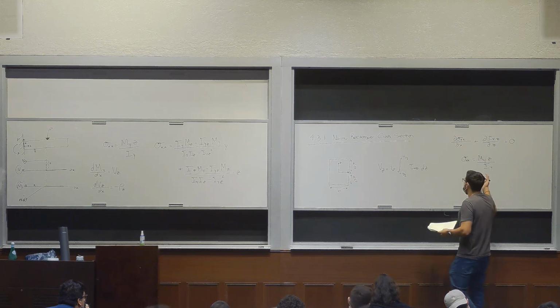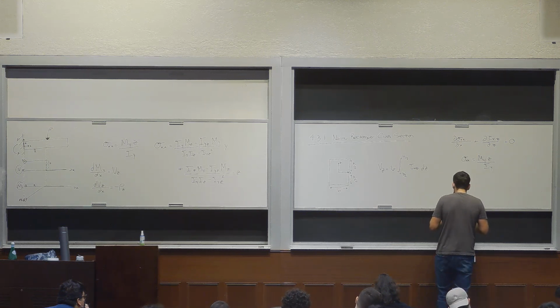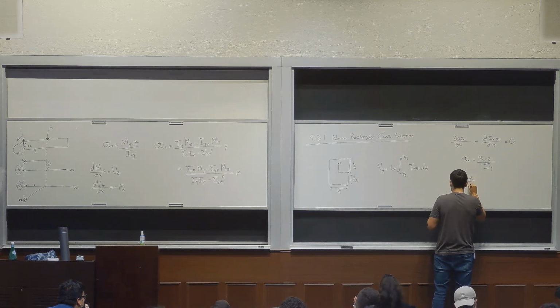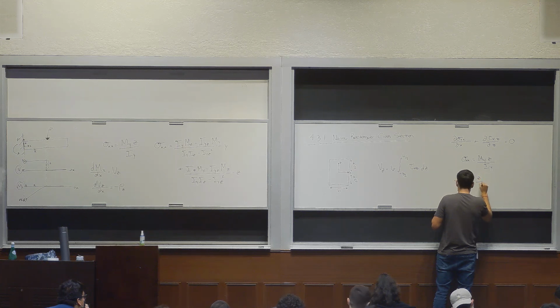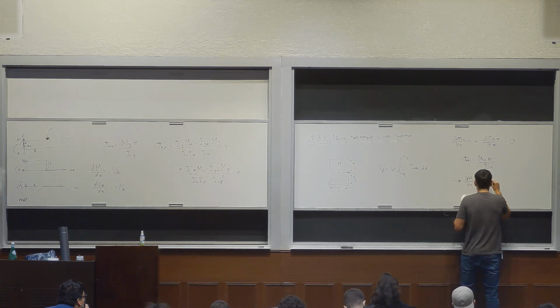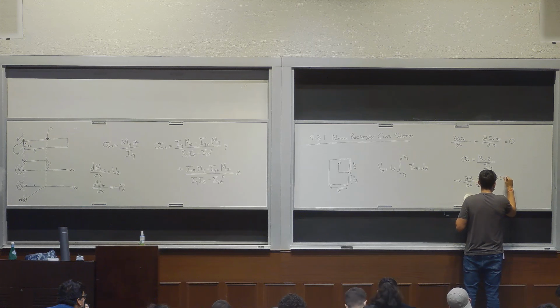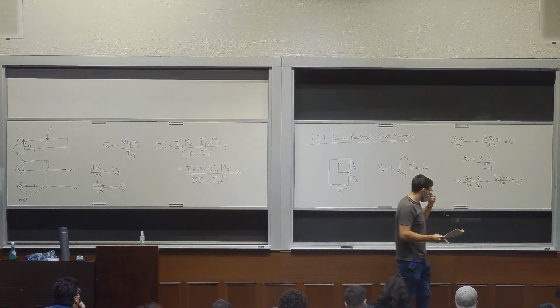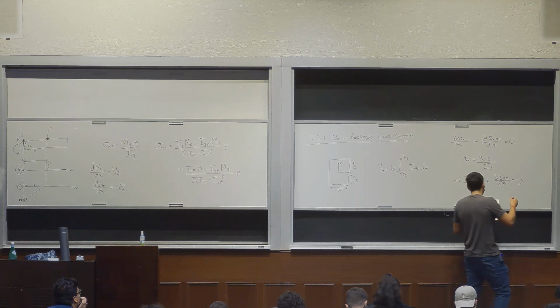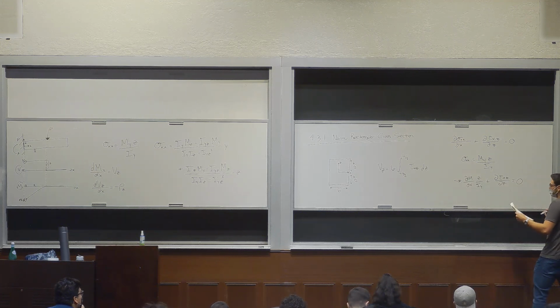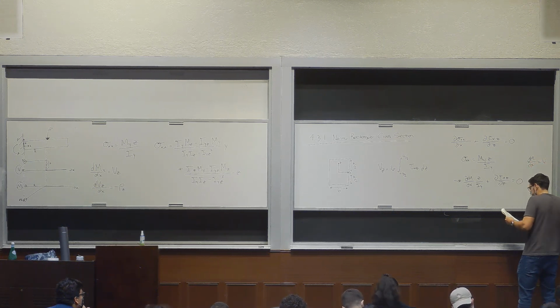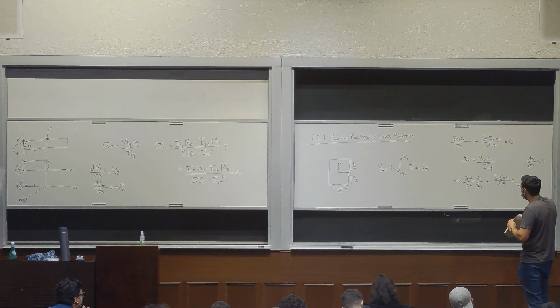We also know that My is related to Vz. So if we rewrite this, actually before we go to that step, as dM/dx, it's the same equation, just rewritten in terms of the moment. But like I said, we also know the relationship between the moment and the shear force, which is dM/dx equals V. It's My in all these cases.